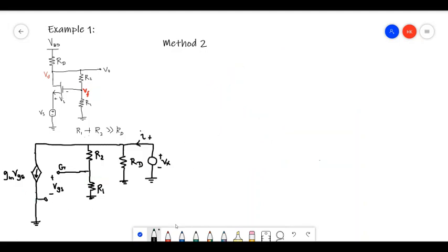Okay, so finally let's calculate the output resistance. So we know what adjustments to make. We need to add this voltage source at the output, and also I have removed the source and grounded it. So now we can proceed to find this. Okay, so Rof can be written as Vx divided by Ix. Right. So how do you find Ix?